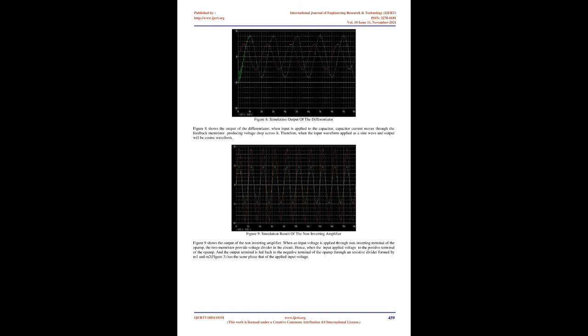Figure 6 shows the results obtained from the simulation of memristor, which indicates the fingerprints of the memristor such as pinched hysteresis curve passing through origin, and with increasing frequency the lobes of the hysteresis curve diminish, exhibiting a linear curve, which were also verified.